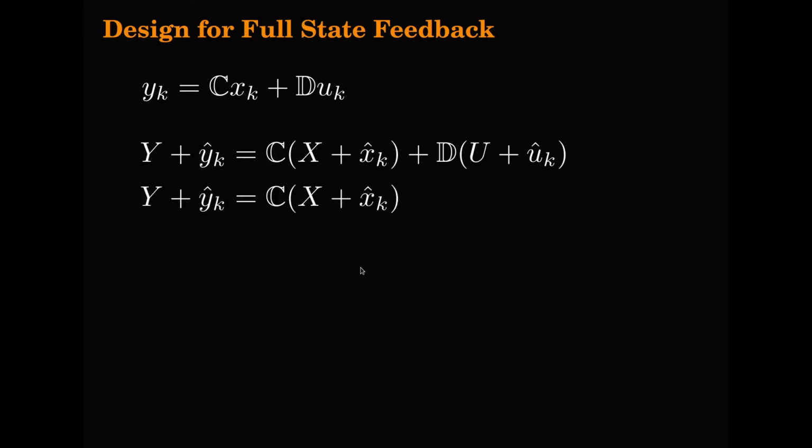So let us take that part which is leading to the dynamics of the system, the dynamics of the state values and the output values, which can be used for feeding back. Y is the controlled output, and this is what you want to feed back, which means that this is what you want to control to some specific value, which means that you would like to set a reference for this particular controlled output variable.